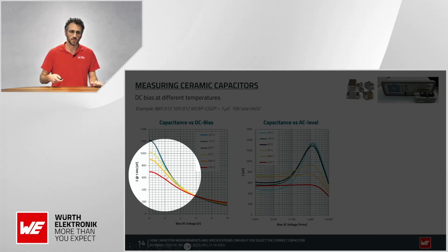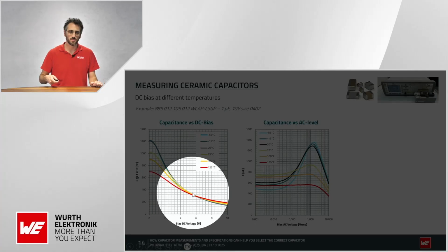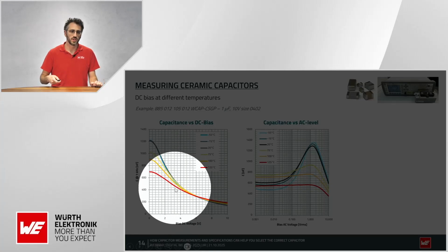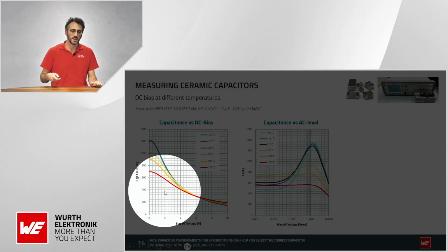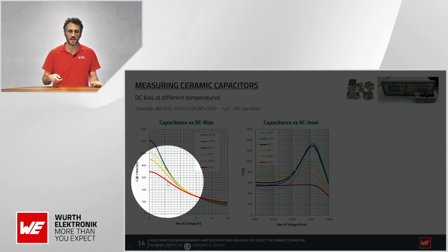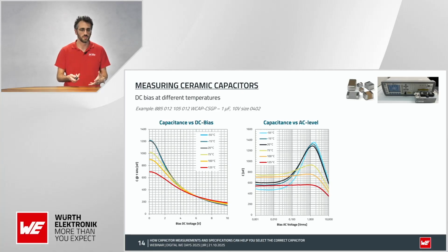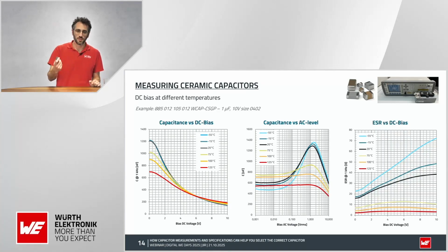But when we include also DC bias, there is, let's say, a saturation of the material, and then we can see that DC bias is what really matters. So the effect is not adding capacitance loss, but is converging. Again, some information about these are not so relevant in this presentation.